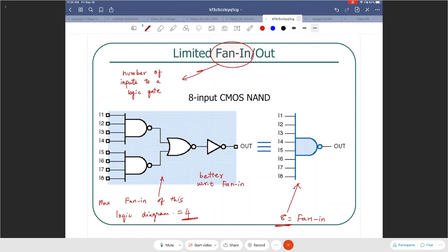Complexity, time. So the increased propagation delay. So the design trade-off over here, well, sure, power consumption is there. There are other things, but I wanted to hit the propagation delay because propagation delay and fan in limitations are direct trade-offs.